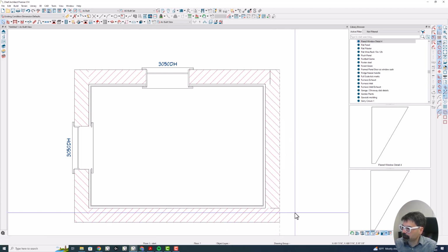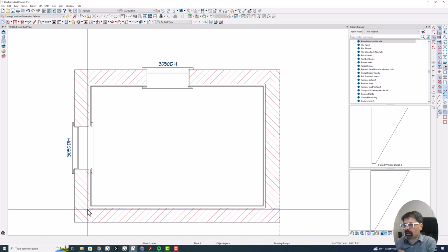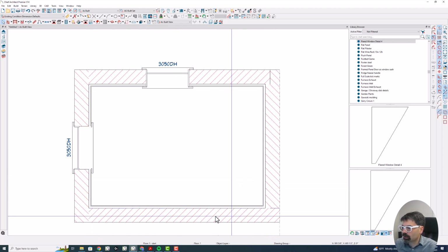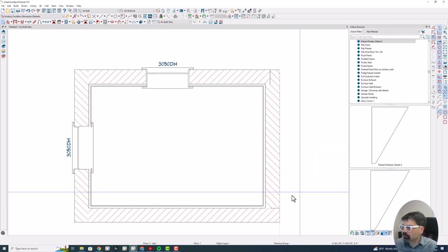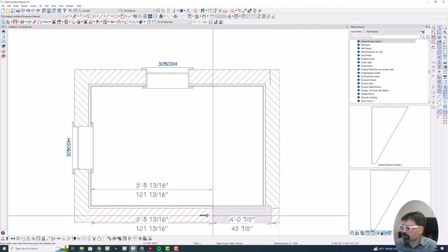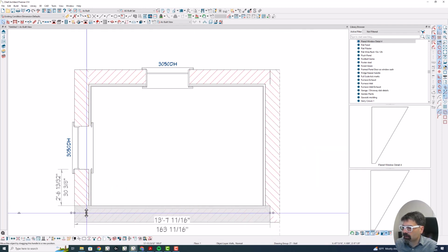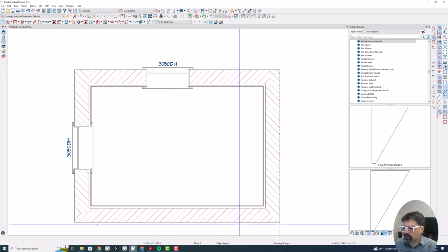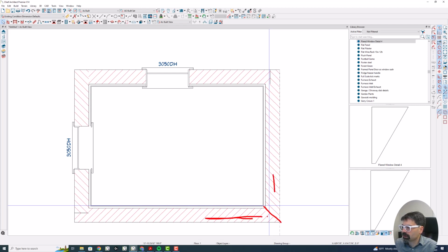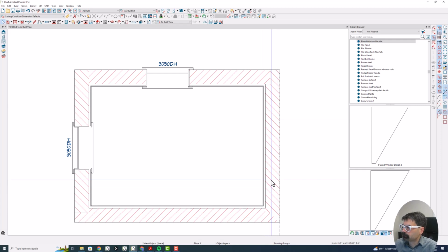Bring it like that. Ultimately, if I were to do this, I would just have the one layer type all the way around. And let's just show that real quick, like that. And so here's that line over here, but back here where there's two wall layers of the same type, there's no black line.